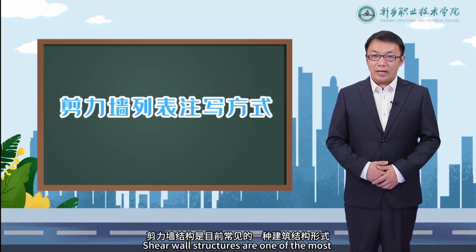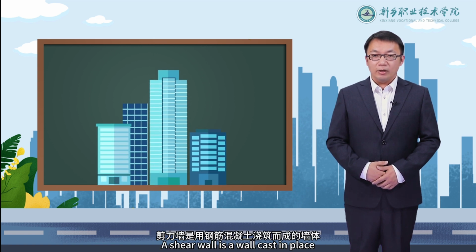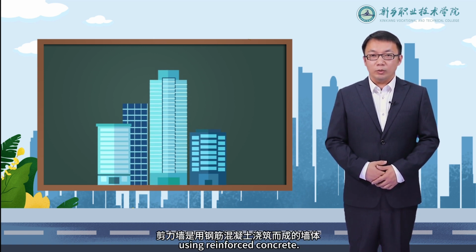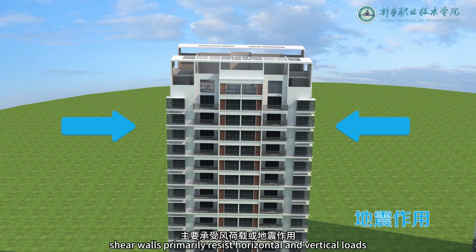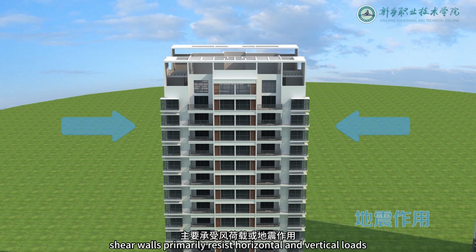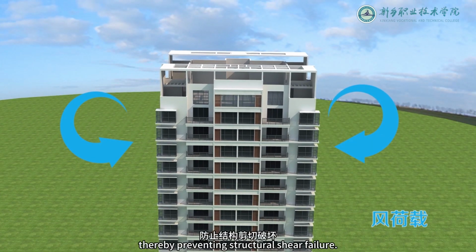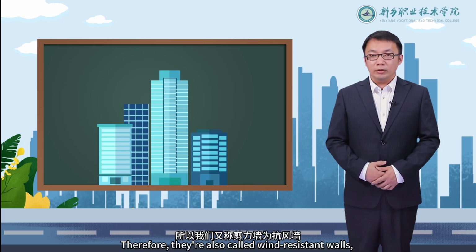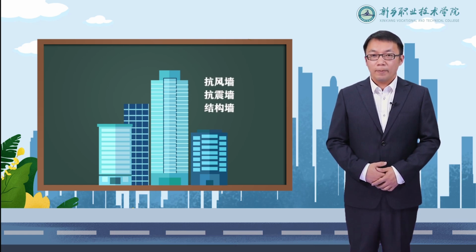Hello everyone. Shear wall structures are one of the most common forms of building structures. A shear wall is a wall cast in place using reinforced concrete. In buildings or other structures, shear walls primarily resist horizontal and vertical loads induced by wind or seismic forces, thereby preventing structural shear failure. Therefore, they're also called wind-resistant walls, seismic walls, or structural walls.